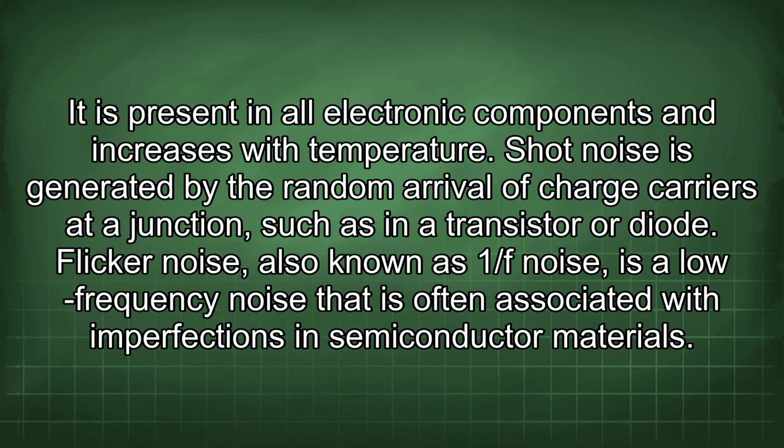Shot noise is generated by the random arrival of charge carriers at a junction, such as in a transistor or diode. Flicker noise, also known as 1/f noise, is a low-frequency noise that is often associated with imperfections in semiconductor materials.